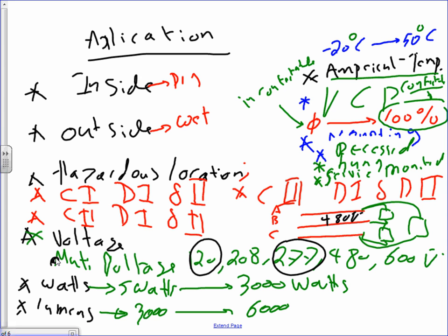There's another concept called VCP. You have to understand this VCP. The way they calculate the VCP is visual comfort probability. This is how they come up with this number. They pay a group of people, guys, the manufacturers. How many of us we have? Let's say we're 10 of us. We get paid to go sit under this light for a couple of hours. And then after you sit under these lights to do a task, they give you a survey.